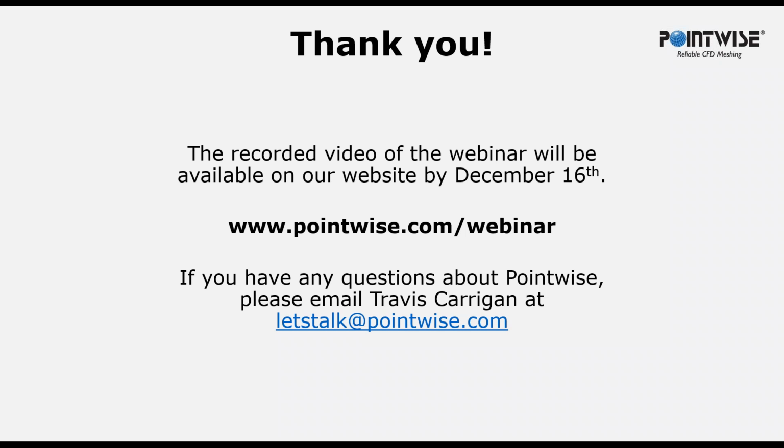Another technique you can use to help save cell count is to go to grid solve attributes for that domain, and you can increase your maximum equilateral edge length for the domain. When you increase that value and you decimate the domain, that will remove interior points from the inside of the domain and create larger cells in the interior. Now, you need to be aware that hitting the decimate command to remove those cells would also clear any T-Rex layers if you're using T-Rex layers on the domain. If you are using T-Rex layers, you may want to use initialize instead of decimate, which would also remove those interior cells but maintain your T-Rex layers.